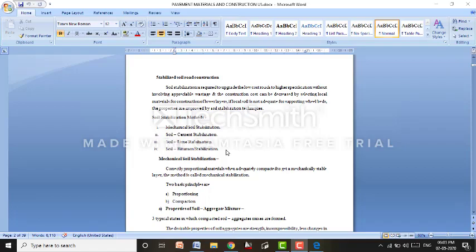At the end, we will be in need of the subgrade with sufficient support, or the earth with sufficient support, so that it can handle the stresses coming from different pavement layers which have come from traffic. Now, to make that subgrade ready for taking the stresses, we need to understand the existing properties of the soil subgrade. Or if the existing strength of that soil is not sufficient to take the stresses, then obviously we will be in need of increasing the property by soil stabilization.